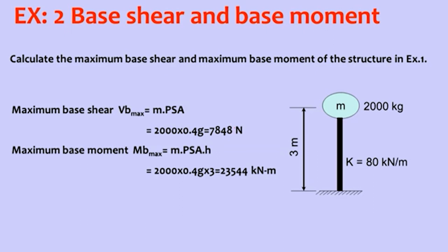Then calculate the maximum base shear and maximum base moment of the structure in the given example, example 1. Base shear can also be calculated in another manner, that is mass into acceleration. So what is that acceleration? It is the pseudo spectral acceleration from the tripartite plot or the response spectrum plot for acceleration.